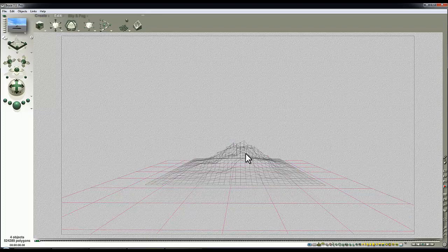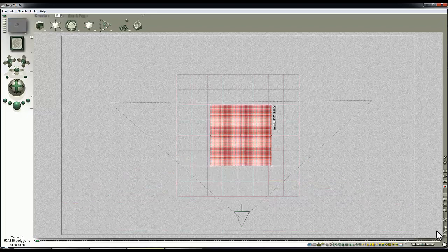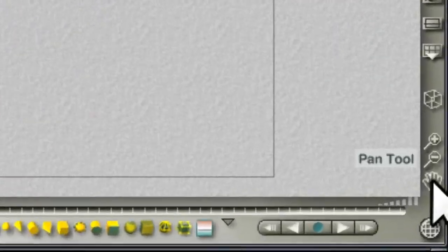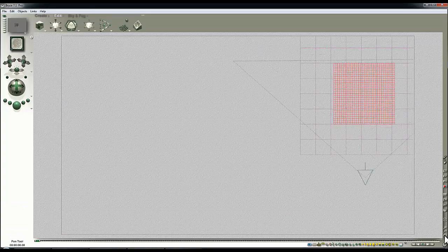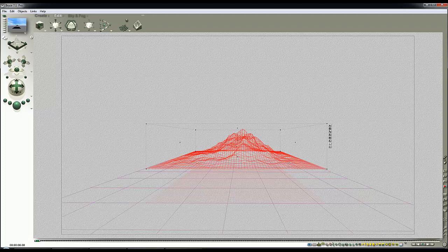I guess we're moving slightly away from our topic here, which was cameras and the positioning of this terrain. So if I switch to number 2, the overhead view, I'm happy to use these zoom controls in the overhead view, and if you need to reposition, there's the hand here, and that allows you to slide your view around. If you use this from the perspective camera, you're going to modify the pan H and pan V options in the attributes, which will change the perspective of the view.